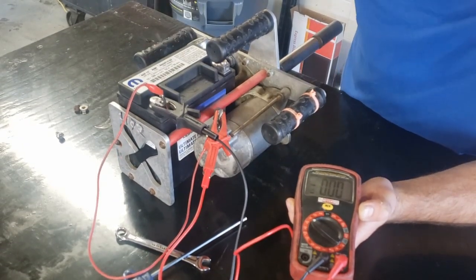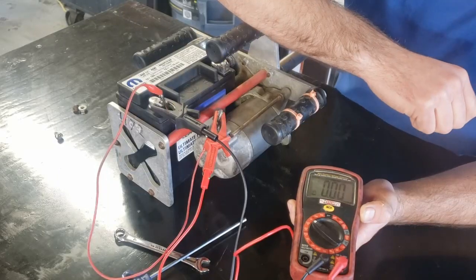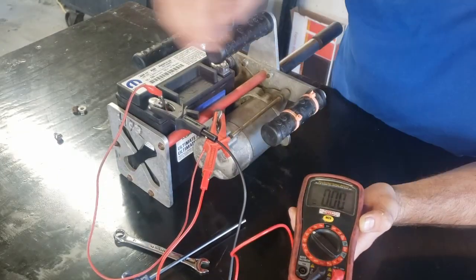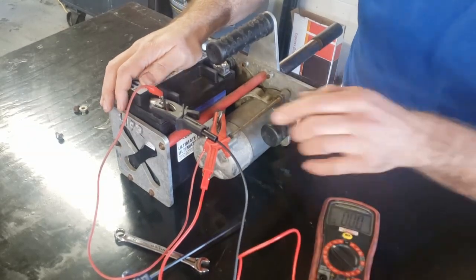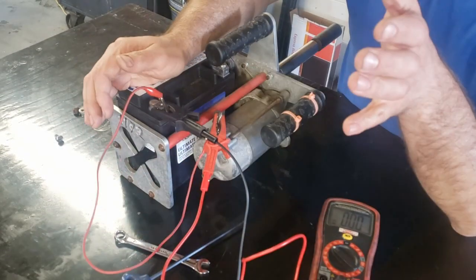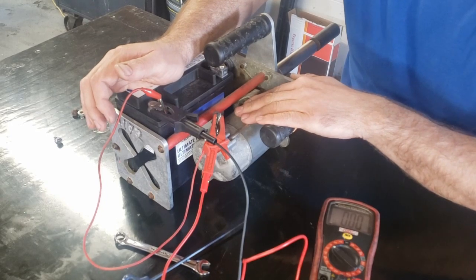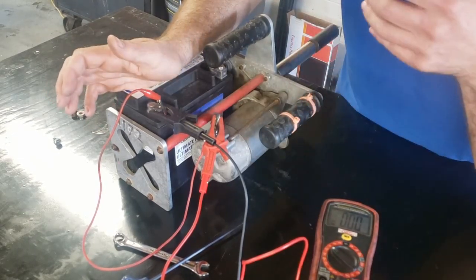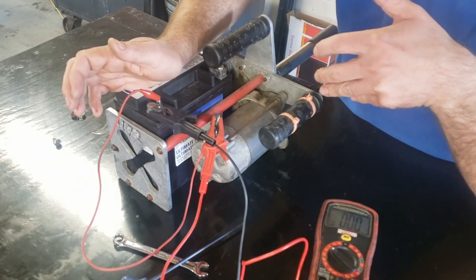And we see a little puff of smoke actually off of the wire. If you watch the meter closely, you saw the reading go up to about 5 volts. So what was happening in this case is I was dropping the voltage across this wire by 5 volts. That means the starter motor, which is meant to see 12 volts, was only seeing 7 volts, which is why you heard the reduced speed of the starter motor, even with no load on it.